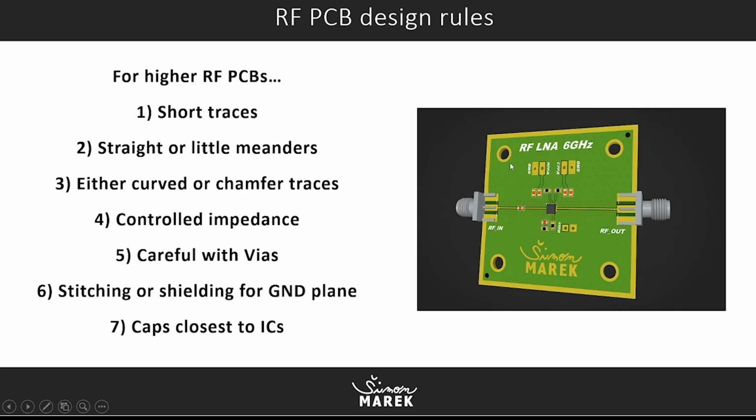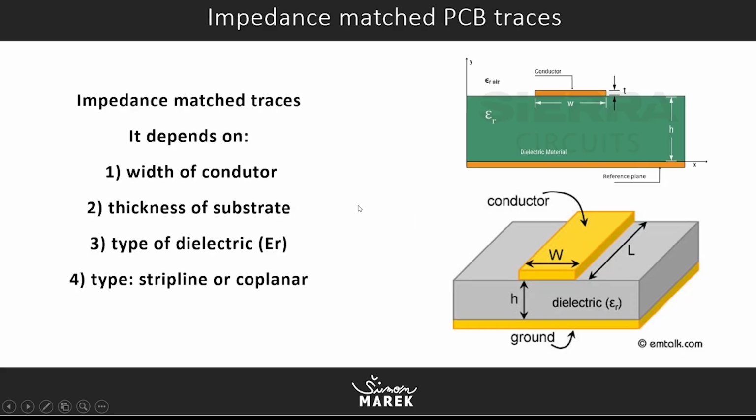So stitching for ground plane, this is also very good practice. And caps should be as close to the IC as possible, so you have almost zero parasitic effects. So this is very important as well.